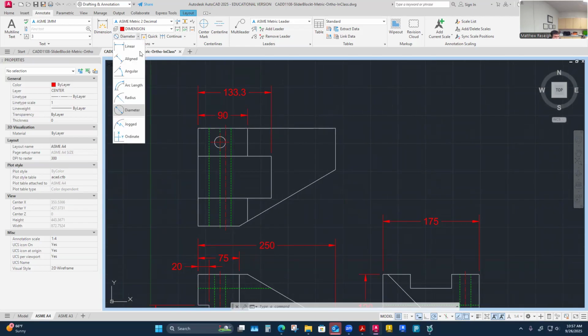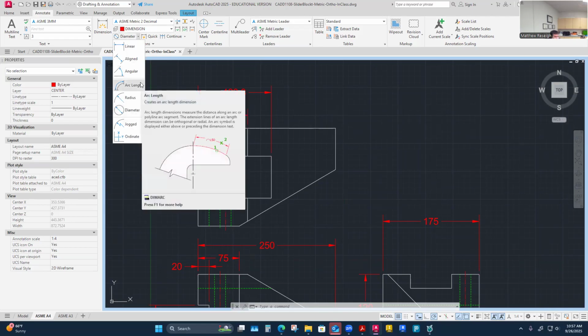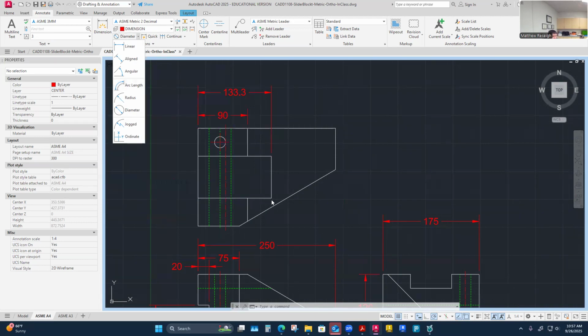We haven't used any angular dimensions yet, but like I say, I use them sparingly. And in this case, I'd probably only have two that I'm applying. I almost view them as more of a reference dimension as well. If the features of this notch were really critical, where the points figured, then I'm definitely going to do the X and Y point to point locating. And I'm not going to rely on the miter dimensions to help me solve where those are. But I might put in the miter dimensions as a reference dimension because it's nice to know.